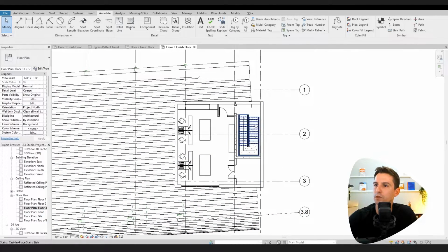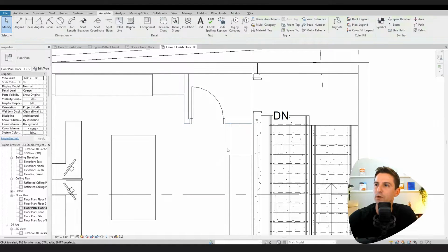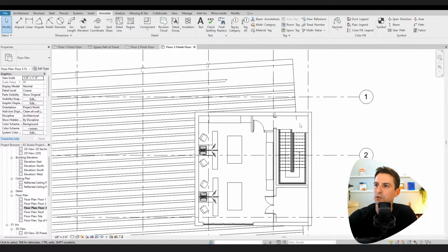So I have just one stairwell here, and that's because there's really not a lot of people that are designed to be up here. And so it's kind of looked at as one room that has immediate access to the stairwell. I have fire-rated partition walls here. This would be a fire-rated door. And so this becomes an extension of that exit going straight down.